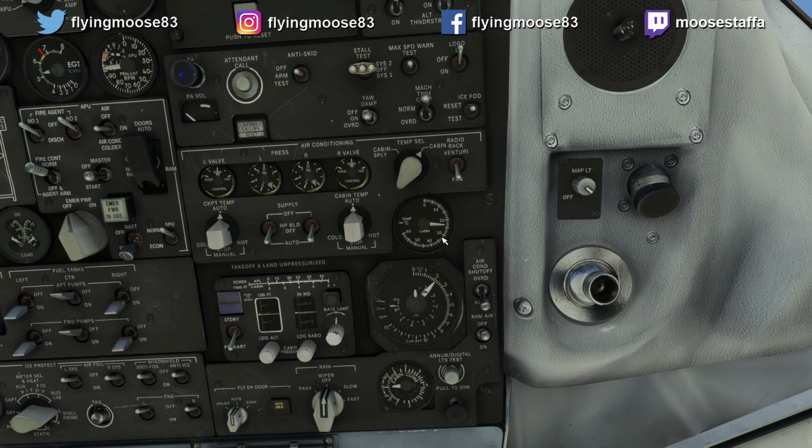This is going to tell us the temperature of the cabin, but it can also tell us the temperature of the supply air coming into the cabin. And so we're supplying it at 16 or so, 17 or so C, and the cabin current temperature is closer to about 23 C. So it's not supplying air as cold as it could because it's trying to hold a relative temperature. So it's going to change the mix manifold.